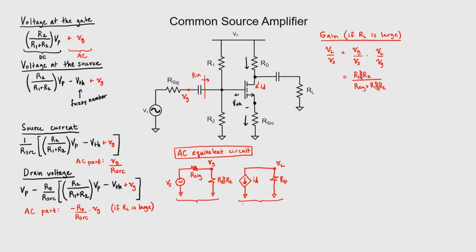From this equation, we can just apply Ohm's law across resistor RD. V equals IR, and the current's flowing up instead of down. For ID, we'll plug in this term, and we now have our required ratio.